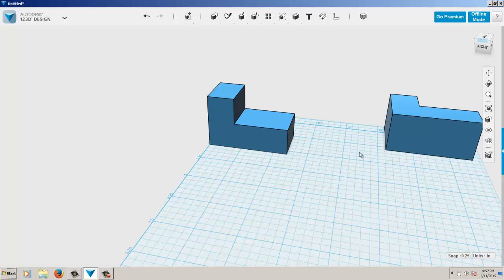Once you've created your part, you can go ahead and get rid of this profile by highlighting it and just hit delete. So there's 2 ways we could have drawn the L block. Another way is we could have started with a basic rectangular shape or this shape and added to instead of taken from. So let's do that.